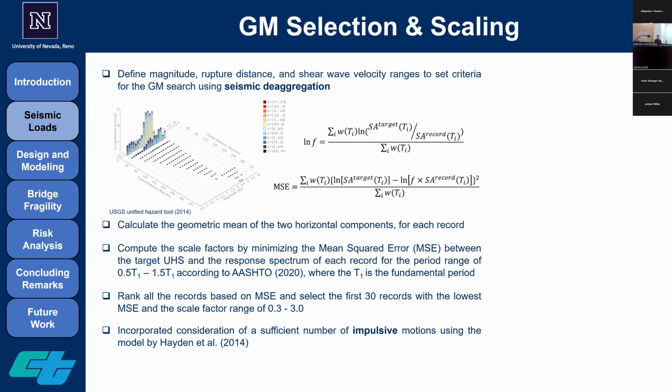Excuse me, you didn't do IDA analysis? No, I didn't. So how do you extract the fragility curve? We have 2 different methods. We can use PSDM or we can use IDA to extract the values for the fragility. Here, since it's nonlinear time history analysis, not incremental dynamic analysis, we're using PSDM, or probabilistic seismic demand model, to do the regression between the engineering demand parameter and our spectral acceleration. Oh, I get it. Thank you.